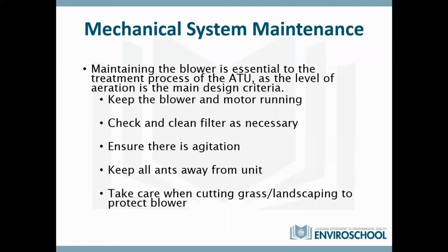In here, I say keep ants away from the unit. You don't want, for whatever reason, ants keep going into these things. I see that quite often. I think it's something to do with the heat, or they can get underneath that housing and it's warm and it vibrates, so it makes them feel comfortable. But ants can tear your motor up.